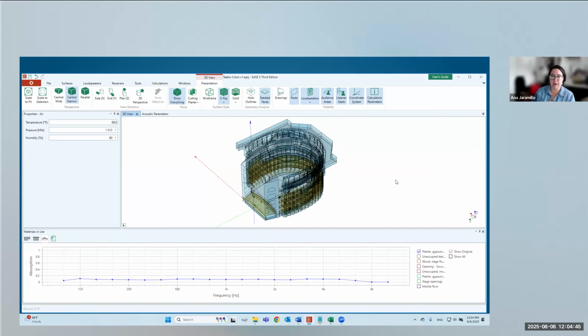There are different ways we could add a way of modifying the vertices and then applying those changes to make sure that coplanarity was not broken at those points. I guess there is no easy answer at this time. If you just need to change the slope, you could rotate a face, but that doesn't mean it's going to have the right length, so that doesn't always work. Sometimes, if it's a square, just redrawing might be easier, or deleting one vertex, moving it, and then re-adding that vertex. I think that's just a strategy for what you can do faster in the drawing.